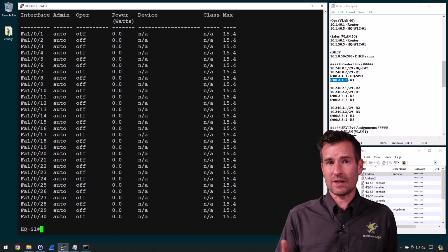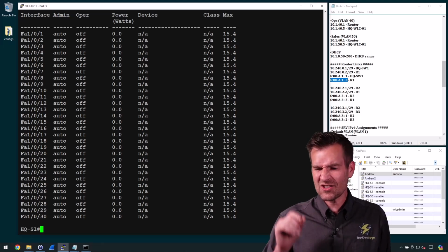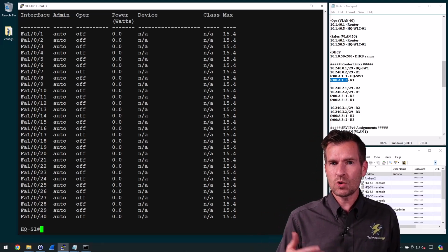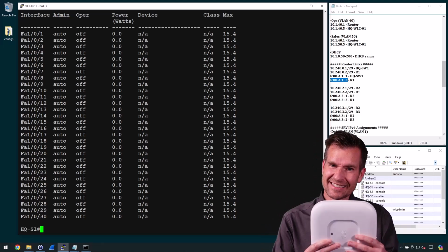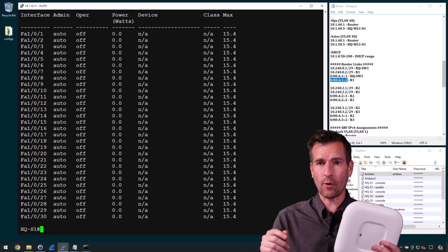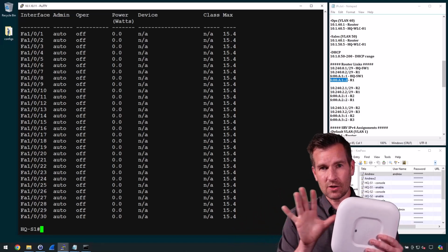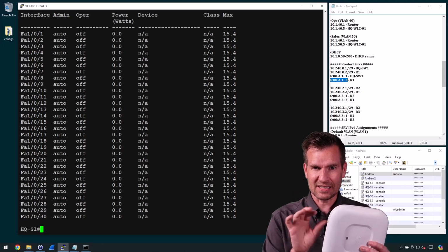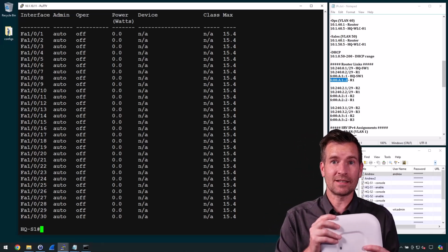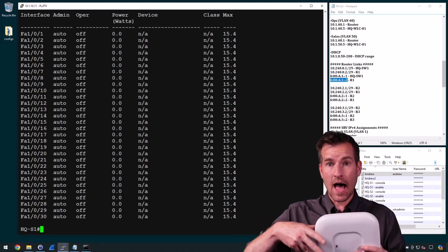Now, it'd be dangerous if my switch automatically assumed that the other device needed power and just started delivering power to it. That could damage certain equipment. So what has to happen is that this device needs to talk with the switch and let it know that it needs power. So I plug this into the switch, and then they start doing this really low level conversation, just back and forth, some really basic signaling to say, I need power to start up. And then the switch provides that power and gets this up and running.